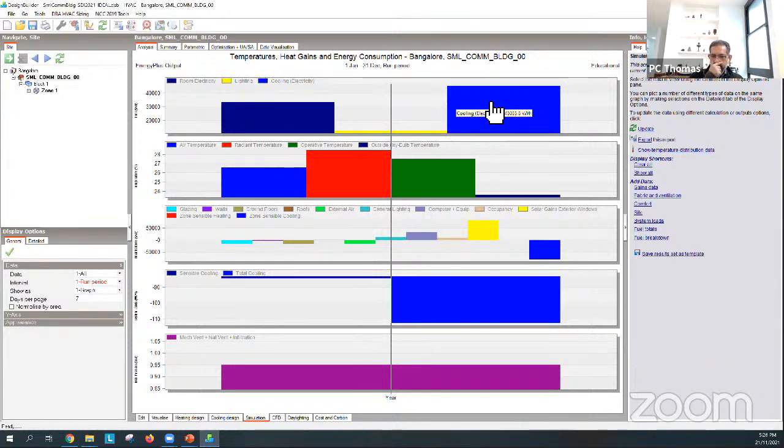So when you're doing your analysis, don't be confused, okay? What EnergyPlus is doing when you use a simple air conditioning system, or an ideal air conditioning system as we call it, is it works out the thermal energy required for heating and cooling. And because we've given it a COP, because we've said it's a heat pump and it's using electricity for both cooling and heating, it uses the COP number that we gave it, and it works out this number for you, okay? So easy enough once you know what you're looking at.